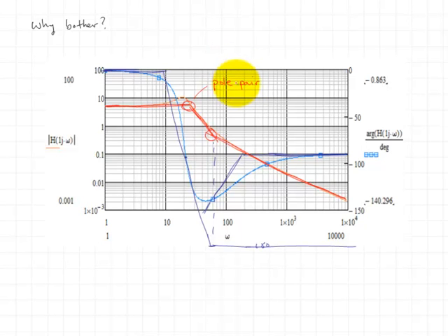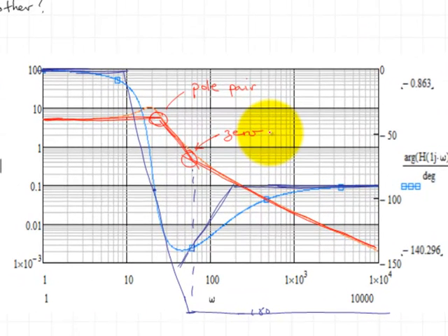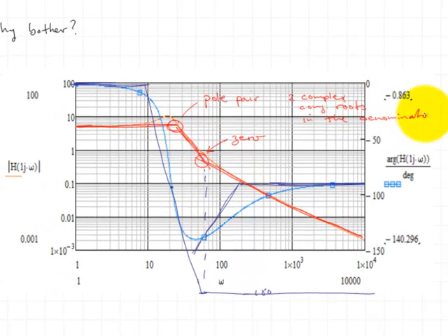There are two poles, and we have yet to define a pole, but essentially a pole is a zero in the denominator of the transfer function. And we have here a zero. So a pole pair is two complex conjugate roots in the denominator. And a zero is, in this case, a single real zero, so it's one real root in the numerator.